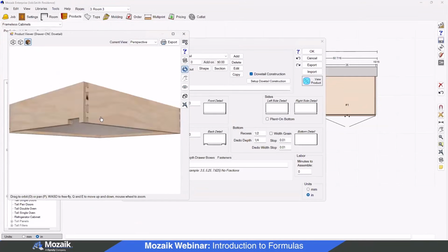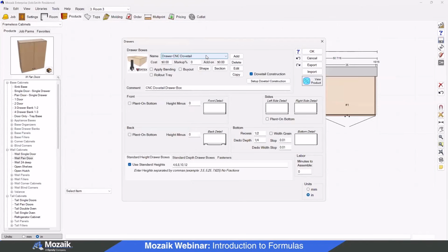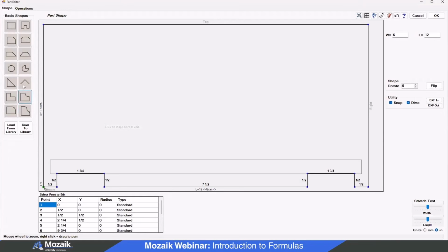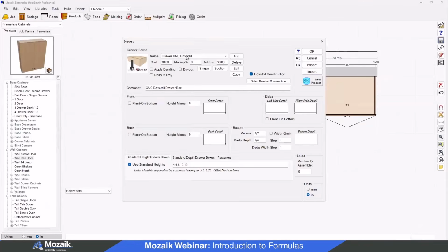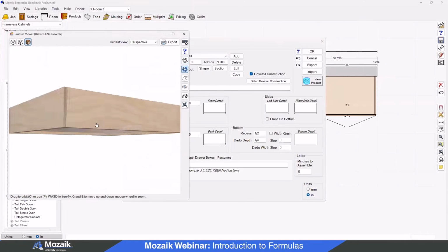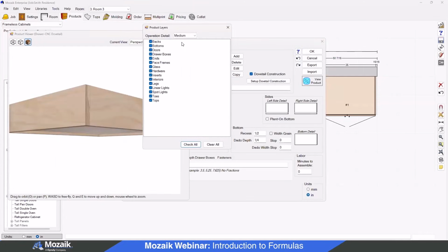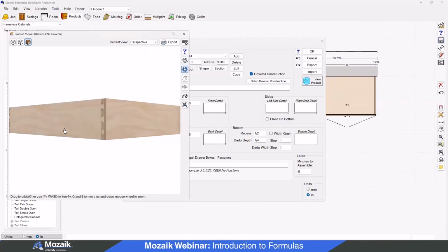So what we're wanting to do, oh, this has already been notched. Look at that. Let's try, let's grab a, yeah, I missed that part there. Let me just bring that back to, all right. Because I think this is going to be how your drawers are going to be showing up by default. So we're going to have no notching in the back end, and I'm just going to show you the process to create that notch.